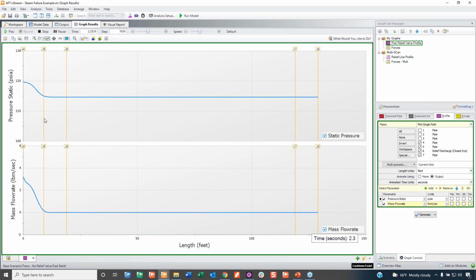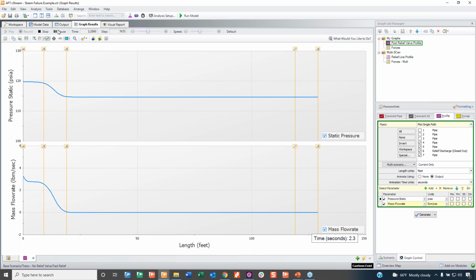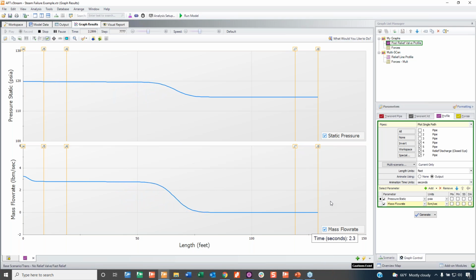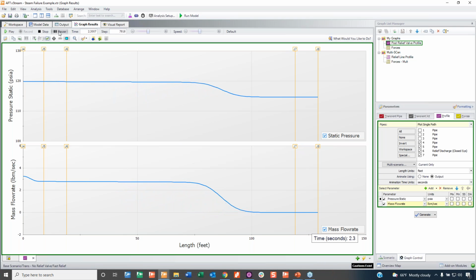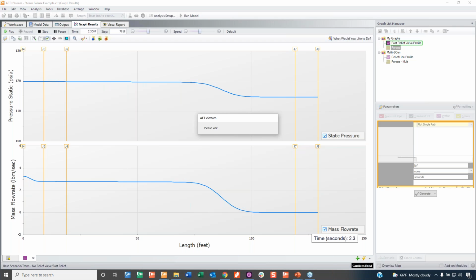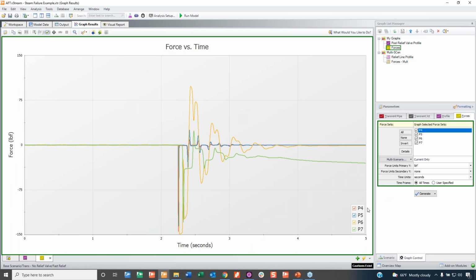okay, it opens, right? The relief valve opens. You see a sudden wavefront of pressure moving through my system. Sudden surge of mass flow moving through my system. So you can see that happening, and this steep nature of this wave, that's because it's such a fast relief. It's so instantaneous that this pressure wave is just moving through very quickly. Cool, so that all makes sense. It's not unintuitive there. That's great.